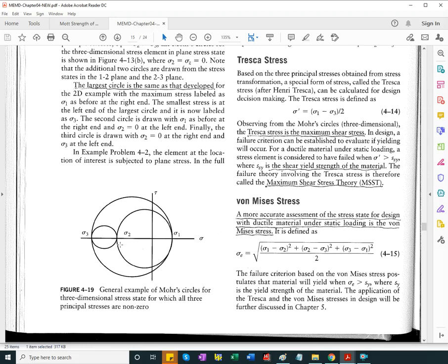This is yet again the case of pressurized pipes, because on the outer surface, remember, there's the axial stress and the hoop stress, both positive, and we have the zero stress perpendicular to the outer surface of the pipe. We're not discussing yet the case of the inside, where sigma 3 is actually negative and equal to the pressure inside of the pipe, or the pressurized cylinder.